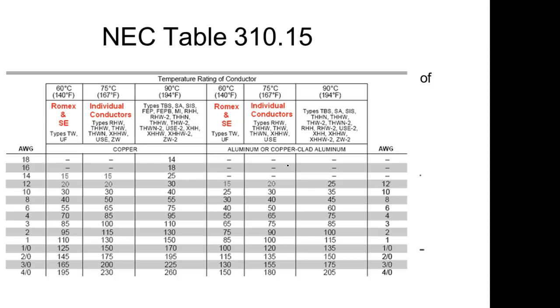And it comes in 3. You can get a 2-wire with the ground, right? Understand? So it has a black, which electricians call your hot one. Then we have the white. They call that what? Neutral, and then the ground. In the NEC, you'll never see those terms.